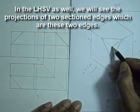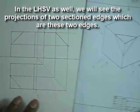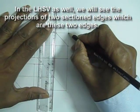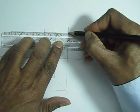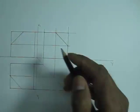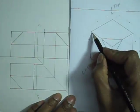This new edge is represented here. Now the inclined surfaces will be projected, so they will be seen as a projected length. So we will draw the projected length of those inclined new edges. This makes the left hand side view of the cube.